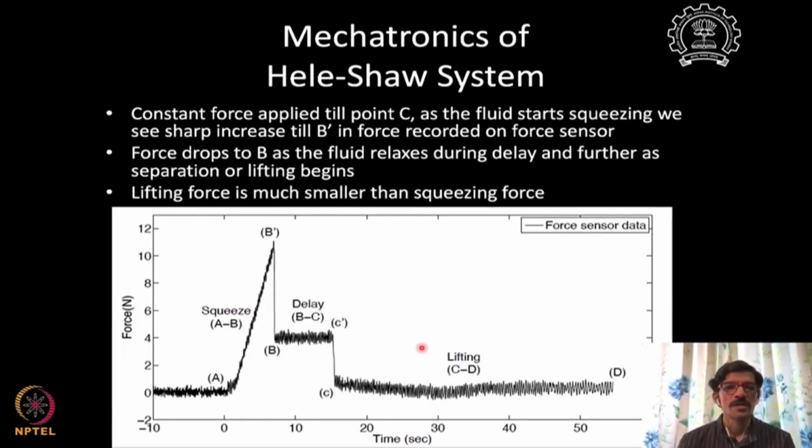We can look at that data. So you see this data is coming from an analog force sensor. This data is a little bit noisy. I think this is after filtering further. We have used some kind of a moving average filter to filter out the data and remove some of the noise, but you can still see some noise, because analog sensors are prone to pick up noise from many environmental places, as we have seen.